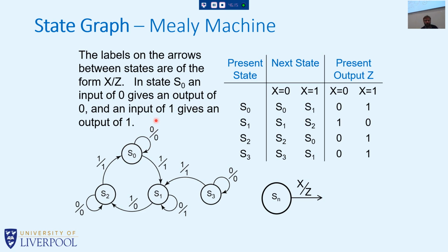So what we do is we write the input and the associated output together instead of the state and the output together. So here's the input and the associated output and the effect on the next state. Input of 1 causes a semi-immediate output of 1 when we're in state 0, but also causes us to cycle through to state 1. Okay, I hope that we've set the scene okay for state machines.